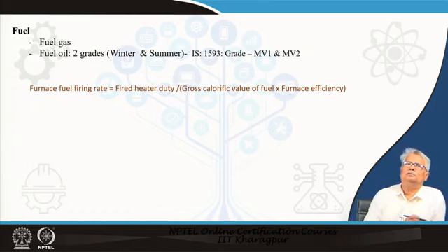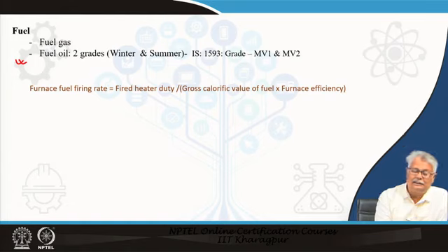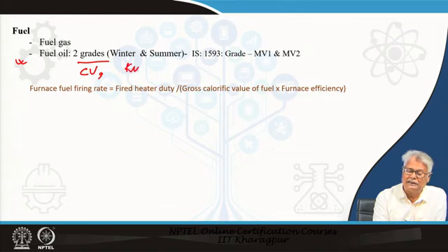Beyond this, we are supposed to look for the fuel. In India, let us look at the fuel oil first. In India, there are typically two grades of fuel oil. And I mentioned earlier that there are two things. Naturally, we are interested in the calorific value, but we are also interested in the kinematic viscosity as well.